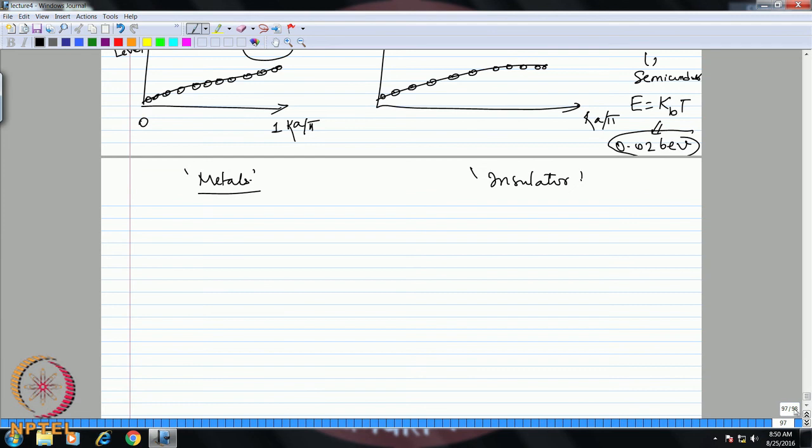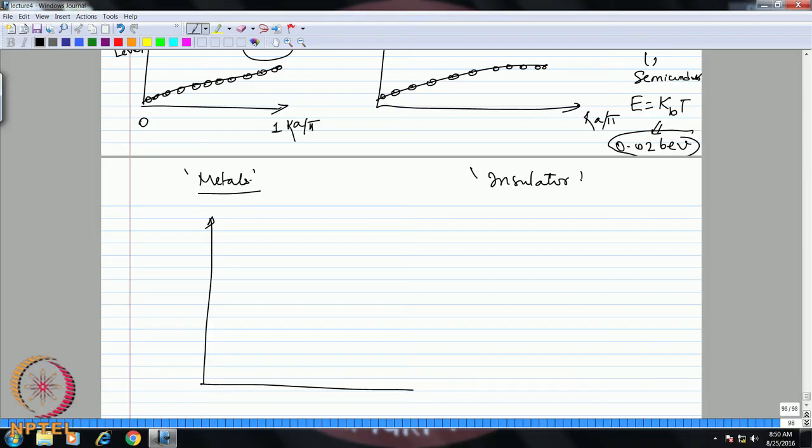You take a donor or acceptor whose Fermi levels can be tuned to be either close to the valence band of this basic material or to the conduction band. Accordingly, it can become an N type or a P type semiconductor. Probably you have heard this kind of explanation when talking about semiconductors, but not in terms of the different energy levels and energy gaps. So, if you look at the N type semiconductor,